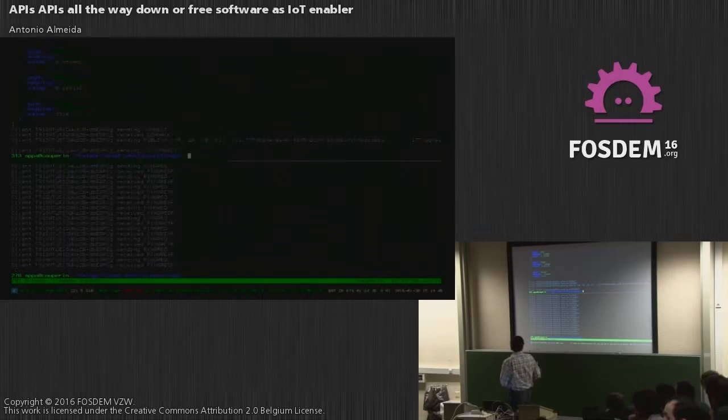I'm just interested here in things that affect humans, and this means the sampling frequency is just 22 kilohertz. I'm not using the CD specification because it's not about hi-fi. I'm interested in knowing what sound affects humans, and you know that's something around 3 kilohertz. So I'm cutting this at 10 kilohertz. So this is what I did.